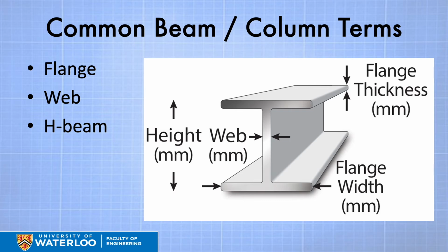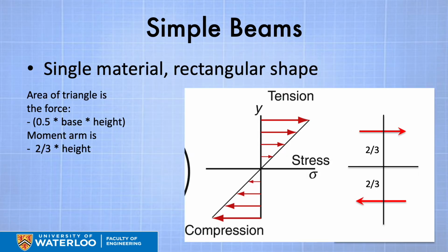These are very common in wood and steel and concrete, I-beams, H-beams, etc. For simple beams, you should be confident to use an equation to assess the maximum stress or the total allowable moment resistance, depending on the shape and the size and the moment, etc. There are pretty straightforward equations for simple shapes that I'm representing here using the triangular stress distribution, which would be assumed for uncracked concrete, wood, steel, aluminum, glass, etc.